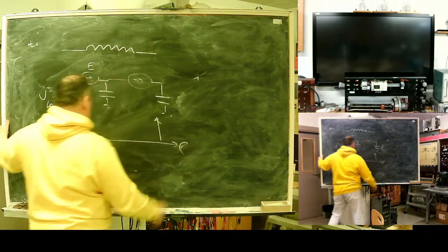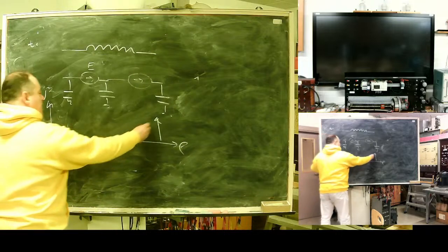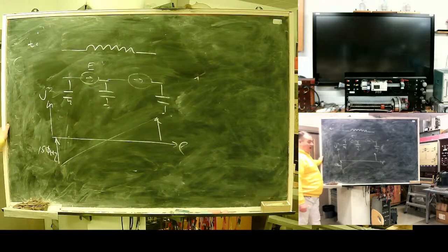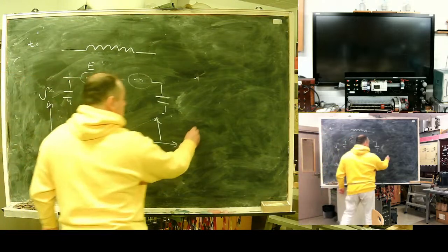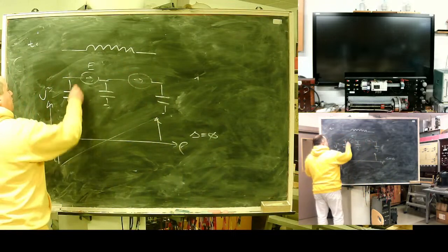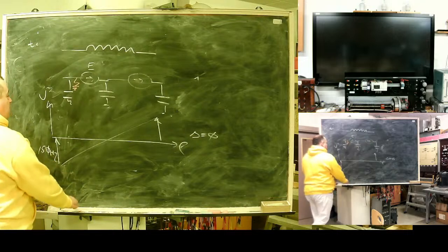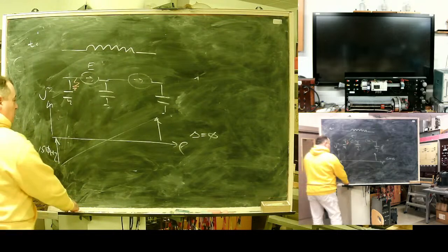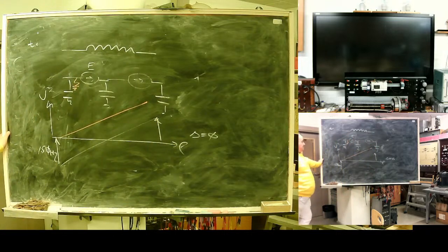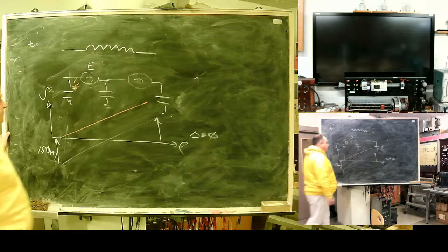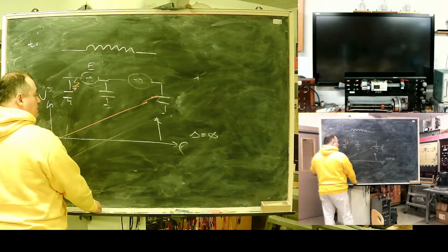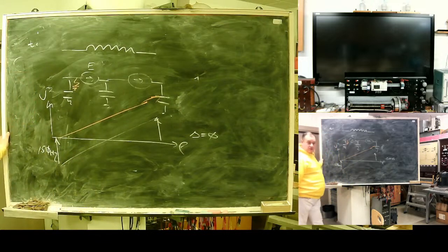Third harmonic along the winding length. If we compare them, on a healthy winding, delta is 0. If, for example, an earth fault happens here, this chart shifts like this. And delta will not be 0.